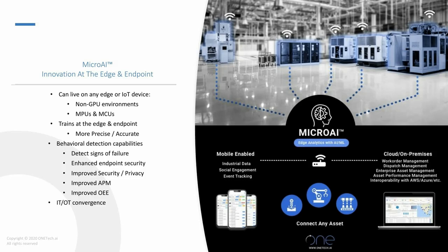And we do this by tying in sensor values, right? So your standard gyroscopic accelerometer, temperature, humidity. We're doing a lot with acoustic emission. So think of little microphones that are listening to bearings and various frequencies.